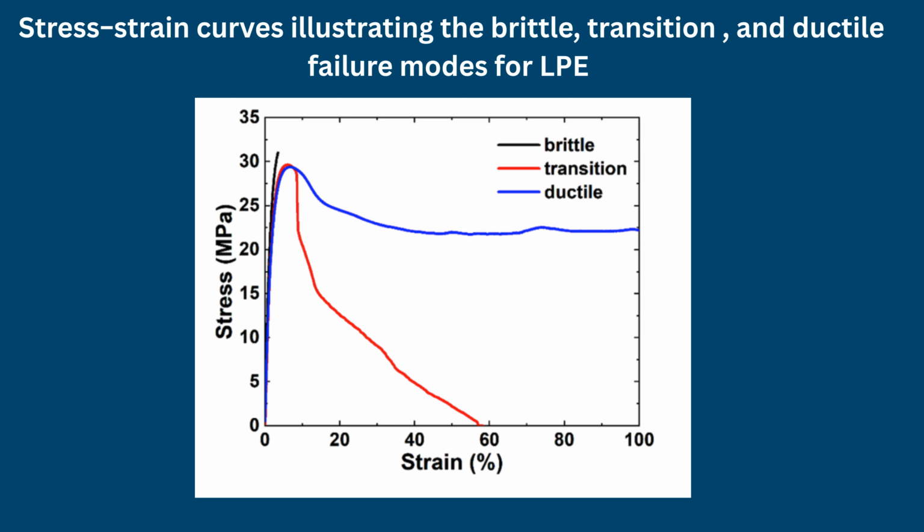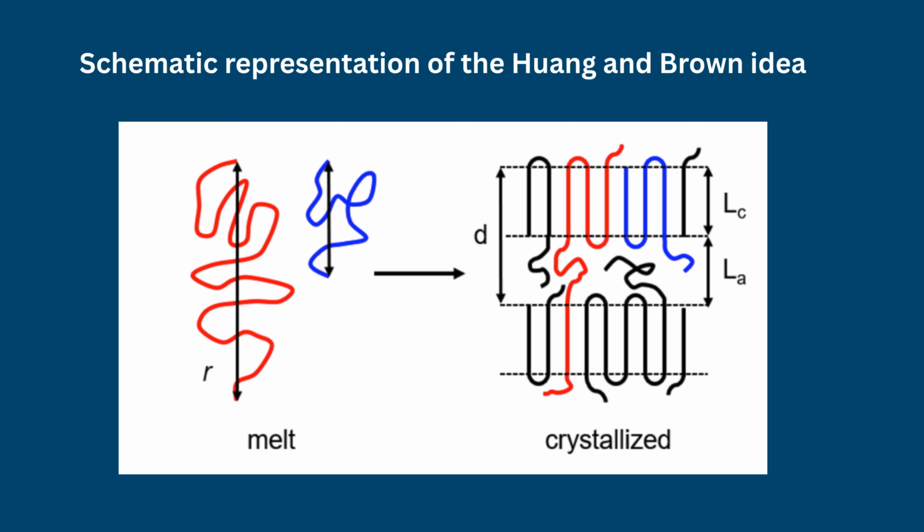However, excessive crystallinity can reduce the amount of deformable amorphous material and alter the distribution of tie molecules. Lamellar thickness is also critical. Thermal history determines crystal thickness and interlamellar spacing. Slow cooling generally produces thicker and more developed crystals, whereas rapid quenching produces a finer morphology.